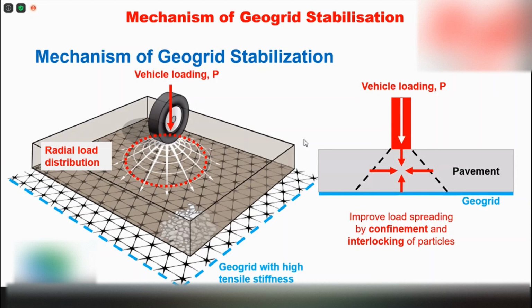But if you do not have a proper reinforcement to distribute this load evenly, of course there will be stress concentration, right? When the stress concentration happens, you will see a cave-in, or rutting as we commonly call it, when the wheel keeps running on the same path. So by having this triax material, which we are not talking about single axial or biaxial, we're talking about triax, which means the grid is in a triangular pattern.